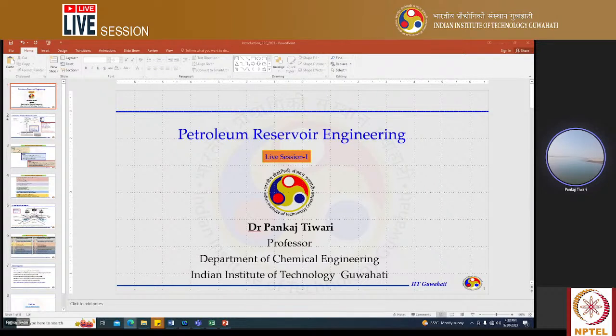That permeability value should be calculated with the information given to you. So you can use the IPR equation, which has the relationship between the flow rate and the pressure drawdown in terms of the reservoir properties and fluid properties. One of the reservoir properties, the permeability, is missing. Otherwise, other values for the fluid and reservoir are given, like the pay zone thickness for the reservoir, well radius, and reservoir radius. Viscosity of the oil is also provided. Now, which IPR equation should you be using? That is the question, correct?